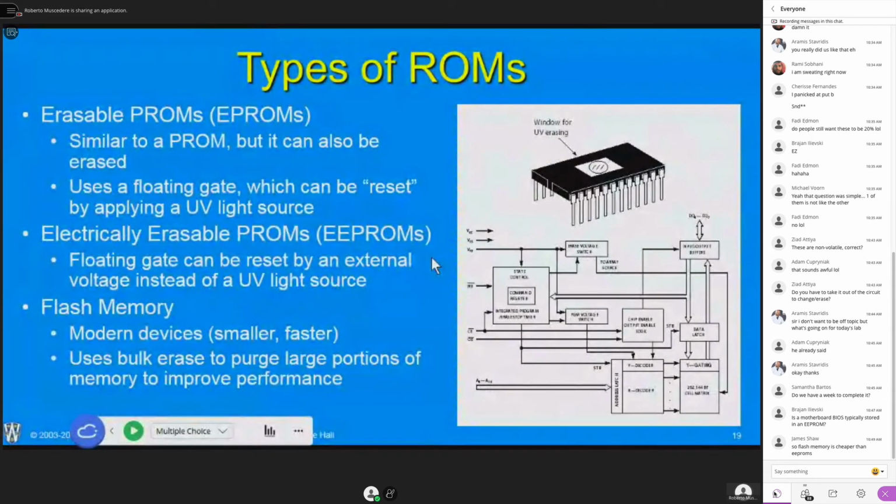So by changing 1 byte, it basically has to read that data back, tell it to erase that part, alter that 1 byte, and then rewrite everything back. So it's a larger transaction. The block size for flash memory is usually 4K, 16K, maybe even larger. So that's what you have to erase. You have to erase large chunks of memory to utilize this.